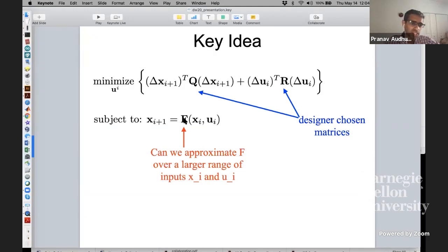Now, people have done this before. They would take a special system, usually one for which solutions are available, like the rimless wheel and simplest walker, or for a hopping model, the spring-loaded inverted pendulum. You can do certain linearizations and get this map analytically, but in most cases you can't. And especially for a more complex model, you just can't get an analytical solution.